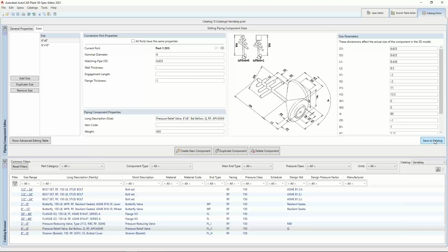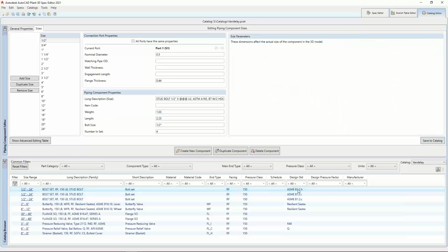Let's change a bolt. Right here, let's do the H one. The C one we're going to change anyway because we changed that bolt standard. But for the H one, remember we can also play with the thickness here because this gets subtracted. So think of it this way: 1.62, I made it a 1/2 inch difference. That's not going to make the bolt a 1/2 inch longer. That will actually make the bolt 1 inch shorter because it's going to subtract that number from the length. So it's now a 1/2 inch longer.